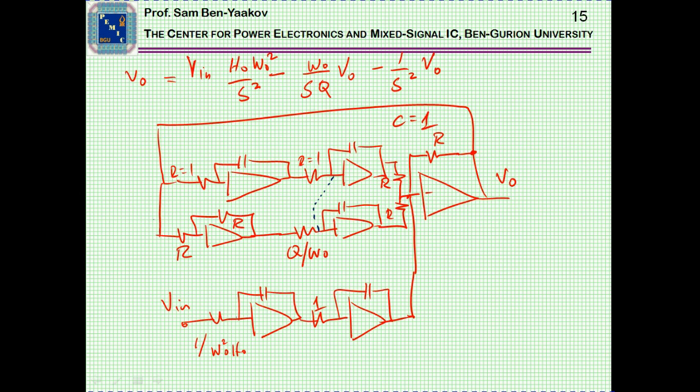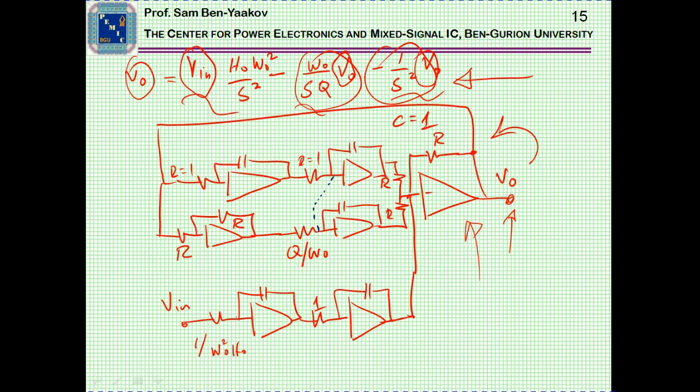So now we have this expression which sort of relates V out to these terms. Notice that in these terms, one term here is a function of V in, here we have a function of V out, and here is a function of V out. So what we are going to do here is actually to go from the end backward. So suppose this is V out at the output of this amplifier. Now we are going to realize these two terms. This is a first order, this is just an integrator, and this is just a double integrator.